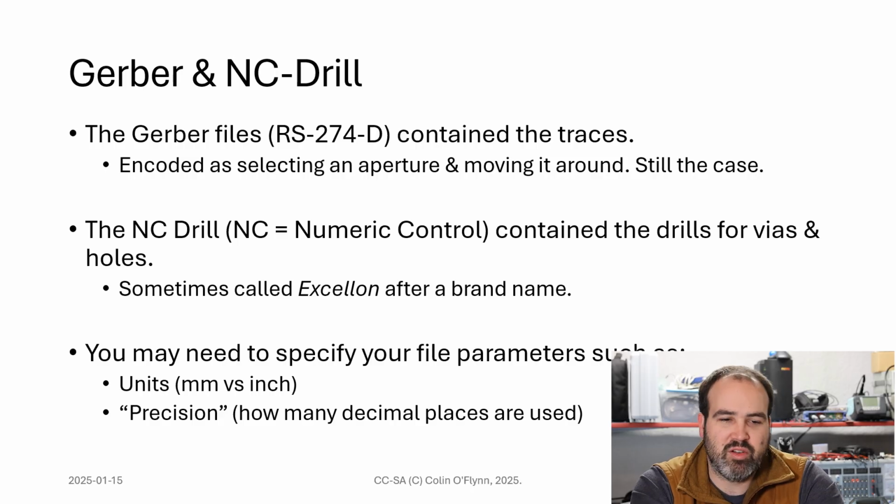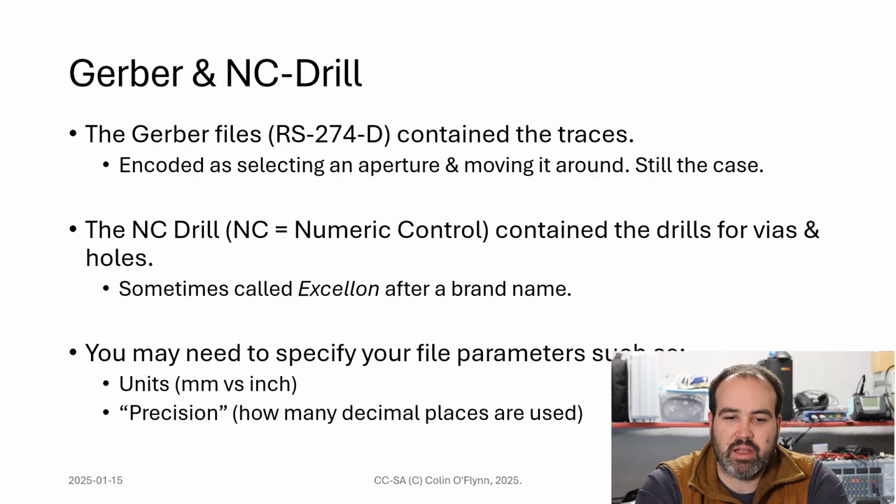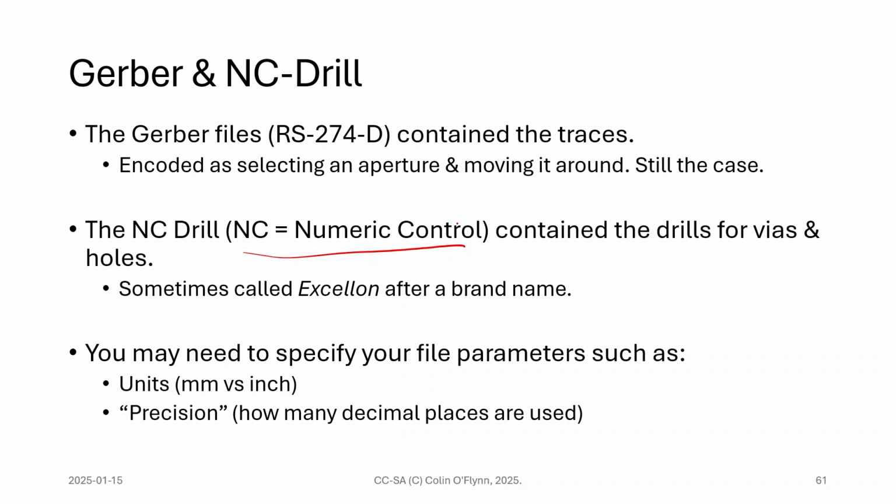The other file is the numeric controller NC-Drill. Sometimes it's called Excellon, which was a brand name, or it has other names, but this has the drills for the vias and holes on your board. It sometimes is split as well if you have slots. With a lot of connectors, you may have a separate file that includes slotted holes, so you may end up with two NC-Drill files.